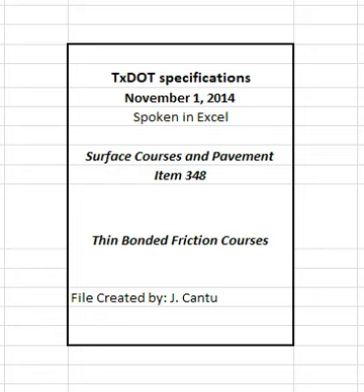Add the recycled binder content to the flow meter readout when the asphalt mass flow meter is used to determine binder content. May be obtained from asphalt mass flow meter readouts. 4 Binder content is not allowed to be outside the limits shown in Table 7. 5 The engineer may reduce or waive the sampling and testing requirements based on a satisfactory test history.